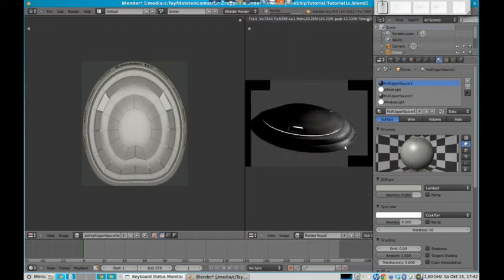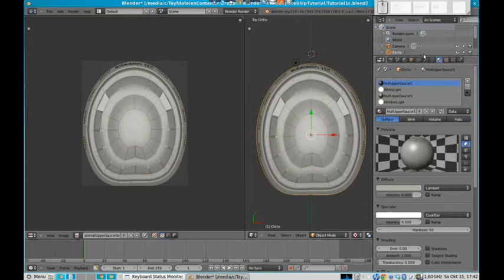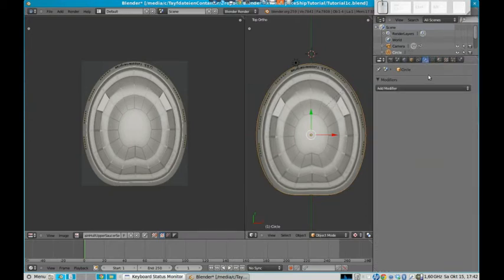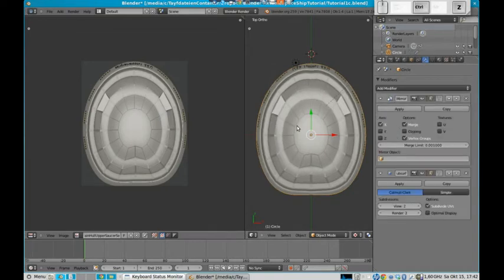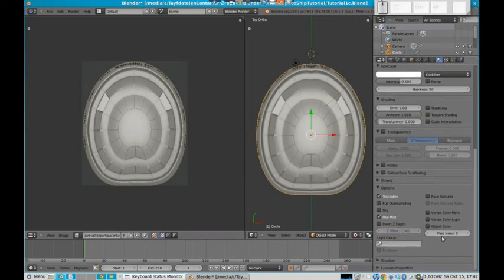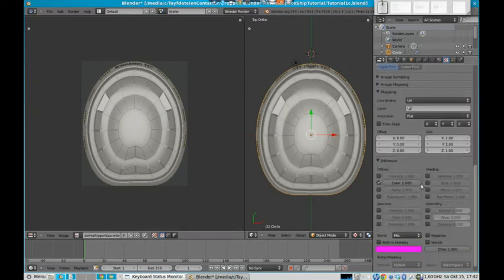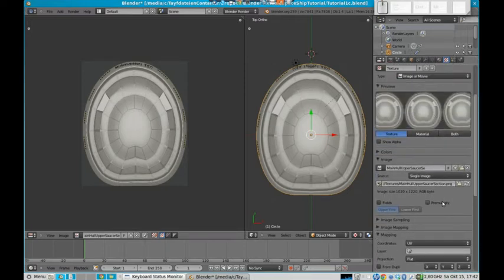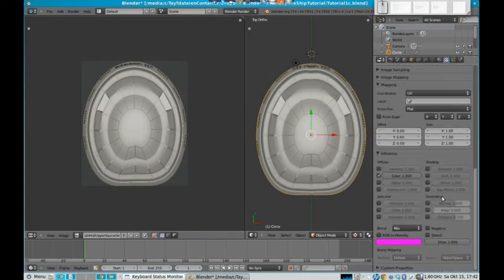And you see now it's correct, but it still has no surface right now. Let me first of all, since we are not finished with modeling, undo these parts, so you know that that will flip automatically at the end. But for now we will just keep it like that and add the bump mapping, which we wanted to do all the time. The bump mapping is here. Just go to the texture which you want to be bump mapped, and go to geometry and activate this normal mapping. In my experience, -4 was always a very cool value.